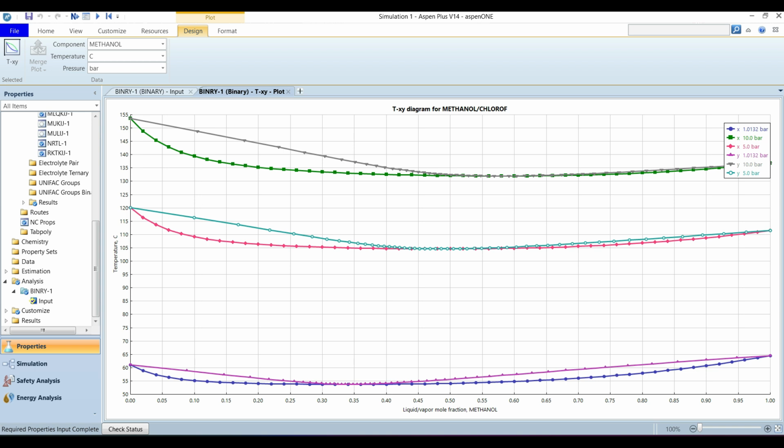So the middle one is the Txy at 5 bar. Again, the first azeotrope at 1 bar was around 35% methanol. Just go to 5 bar at the same composition. Still this point is in the two-phase region. That means even if you operate at 5 bar, that will reduce the cost of the reboiler and the condenser of the second column as well. Also it will reduce the energy requirement for the pump. Still you can appropriately work with the distillation operation. So that way you can try different pressures.